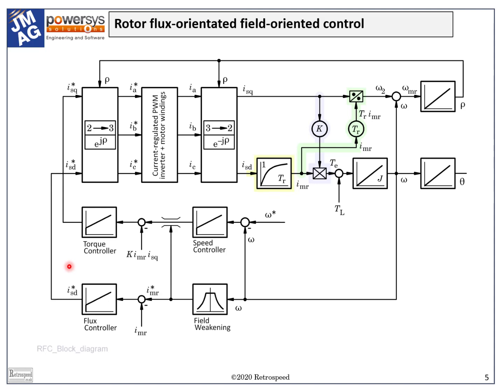This example is for the field-oriented control of an induction motor. It's one of the earliest schemes attributed to Felix Blaschke and Siemens in the late 1970s, and marvelously described in the books by the late Professor Leonhard. Let's look closely. Here we see three currents IA, IB, IC, real numbers whose values are the actual instantaneous amperes flowing into the respective motor windings. They are measured by current transducers located in the output leads of the inverter and therefore in series with the motor windings.